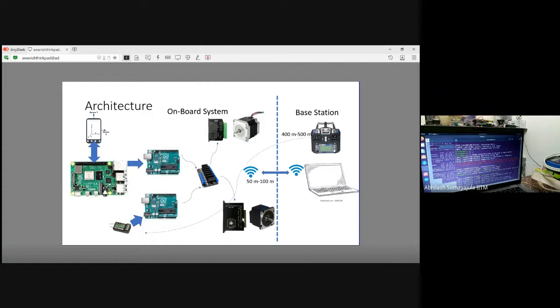I'll show you where it is written. It has three feedback signals coming from the motor, mounted on the coil. It gives you the position of where your rotor actually is. The Hall sensor basically tells me the position of the shaft. It kind of encodes the position of the shaft.